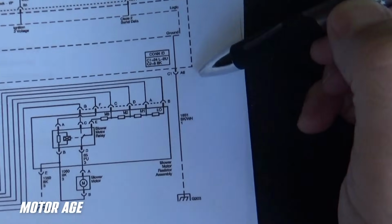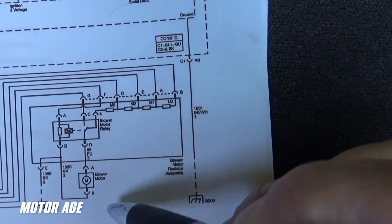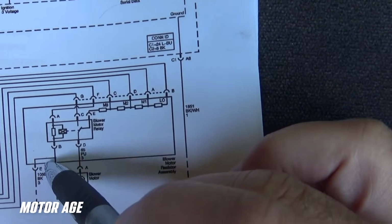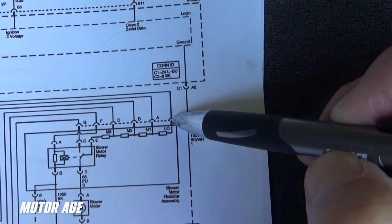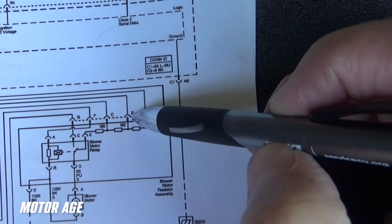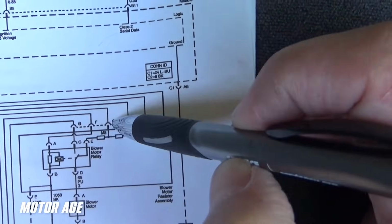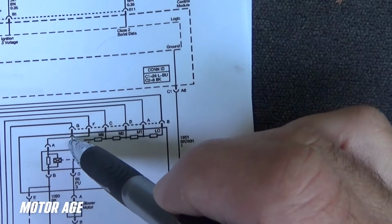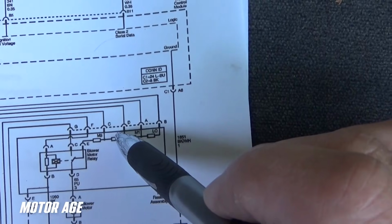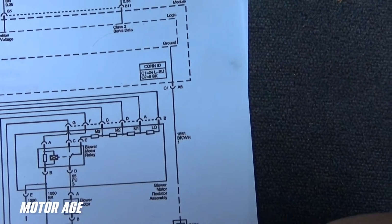So as always, we've got to ask why. Why is there no voltage output to the blower motor in position number 1? Well, that means we've got to step back. We're going to be placing our test lead right here. I'm going to leave my black lead here because it references ground. We know it's a good ground. And we're going to be testing right here. It's obvious all these other ones have integrity because we get voltage down at the blower motor when we were in switch position 5, 4, 3, and 2, but not in position 1.